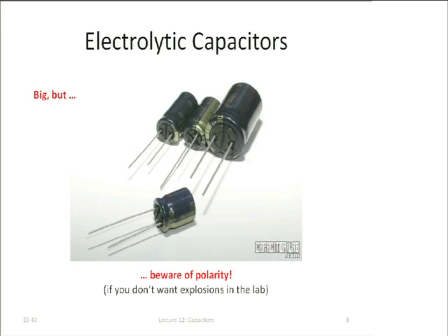There are also very big capacitors, and those are usually so-called electrolytic capacitors. There is some chemistry going on inside to be able to store an incredibly large amount of charge. And I just want to point out something, and that actually says it here, beware of polarity. If you look at these capacitors very carefully, you will see here minus signs, and if you were to turn it around to the other side, it would show plus signs. So you have to hook those up correctly. You have to make sure that the one end is always more negative than the other, and just be very careful.